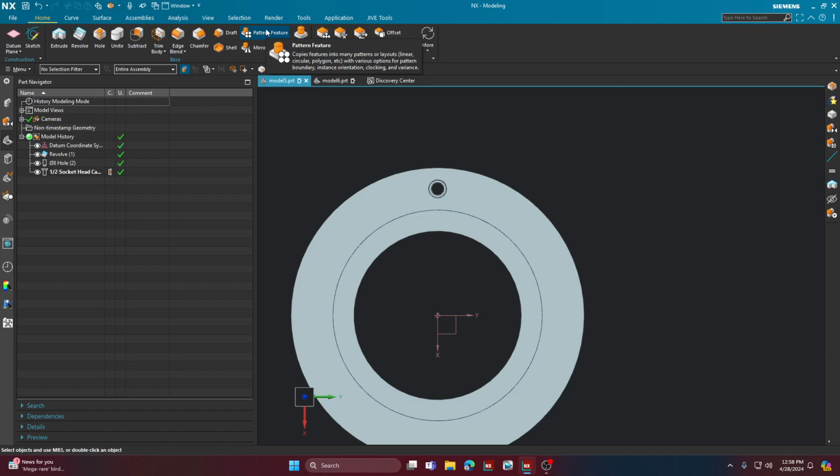Okay, I always explain it in this manner. Imagine that you're patterning a turbine blade. Are you really going to sit there and select every single feature that defines the turbine blade? No, right? Sometimes those features won't even work when it comes to patterning, right? In that case, you just want to take copies of the geometries of that turbine blade and pattern them. You don't really care how they were made, you just really care that you're patterning that particular geometry.